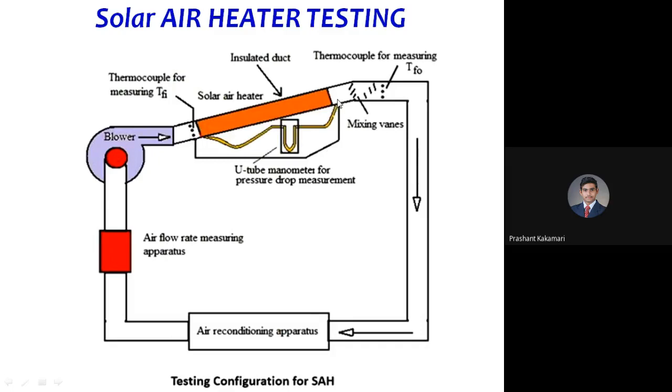Okay, so to overcome this change in temperature from top to bottom of the duct, what we have done here is use some vanes, small blade type, to achieve mixing of the flow. Once this mixing of the fluid starts at the entry and outlet of the vanes, after some distance at some section, I can assume that the entire duct from top to bottom has the same outlet temperature. At that point, I will connect some thermocouples for finding the outlet fluid temperature.